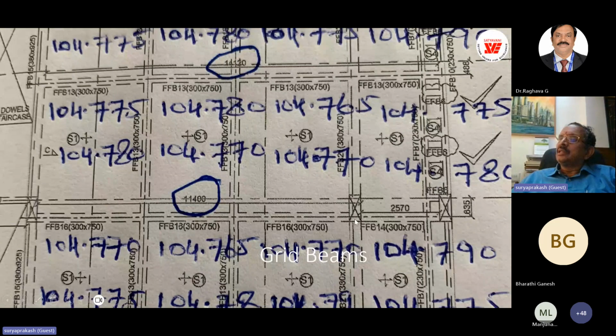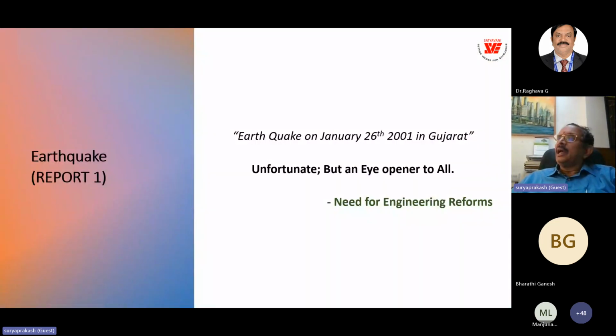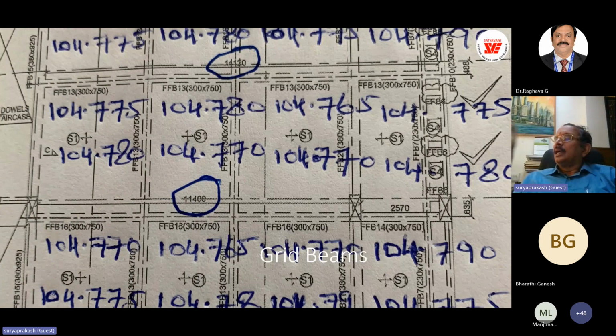And these are the site notes that the engineer has made. Levels are recorded. There was excessive deflection, and so we had to give the entire stitching of the joints using structural plates and shear connectors. And this was repaired, restored, and rehabilitated the structure.